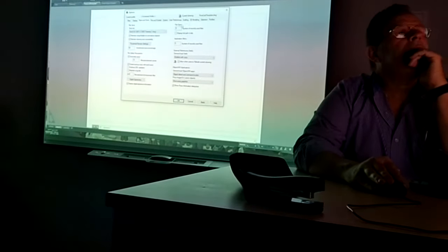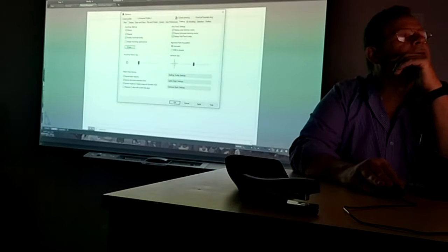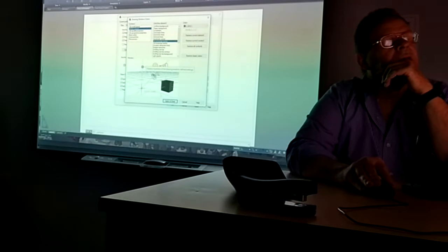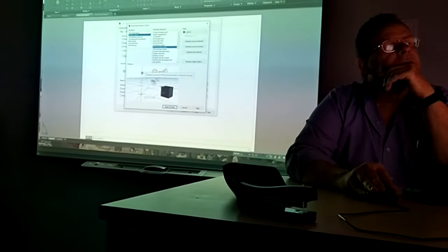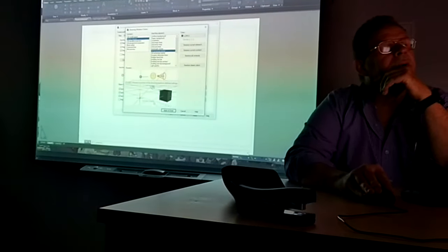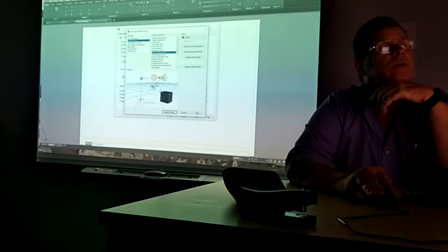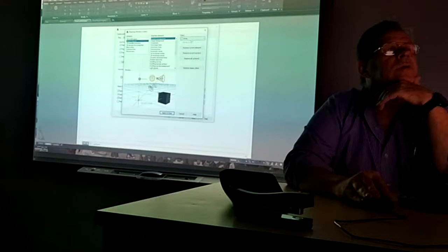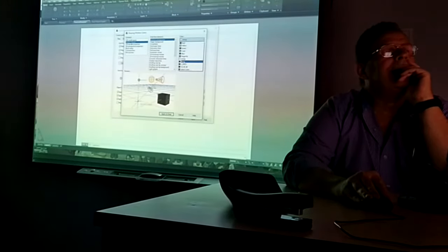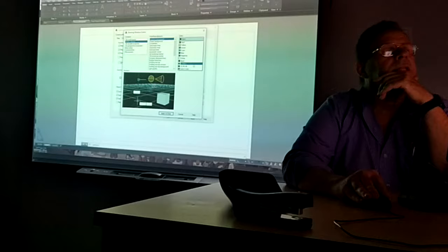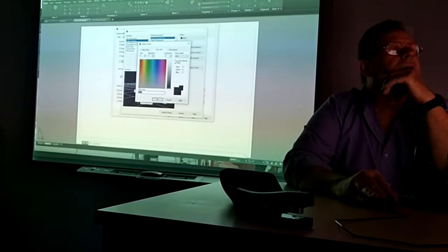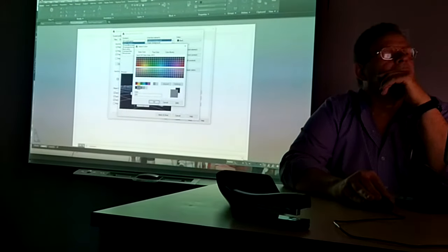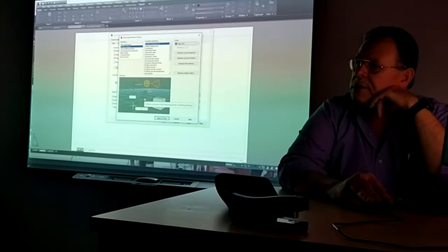Then I go to the Drafting tab, Colors, and over here you see this little monitor screen. It's a mini one. You can see the white background with some objects. That's telling you what you've got. So here on the uniform background, and over here on the color, I would change it to black. Some people like to select, under index color, a dark gray, and you still get a nice, darker background.